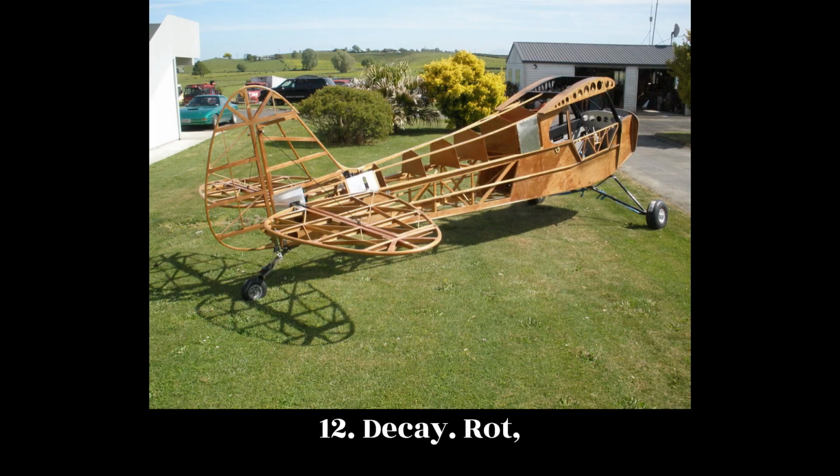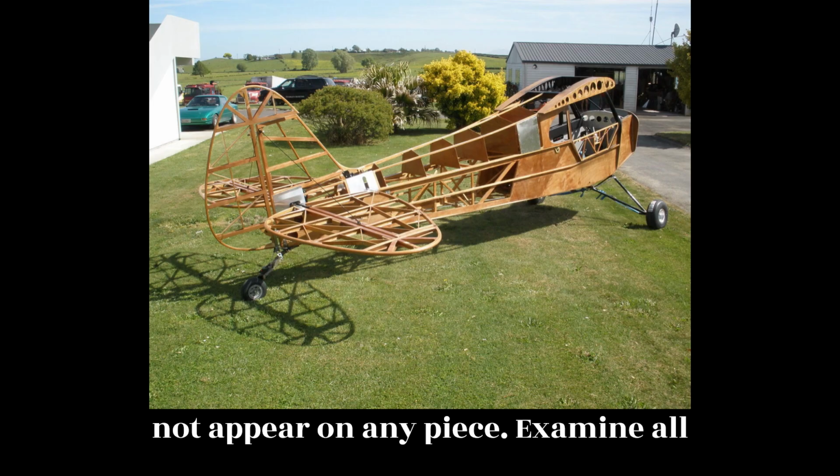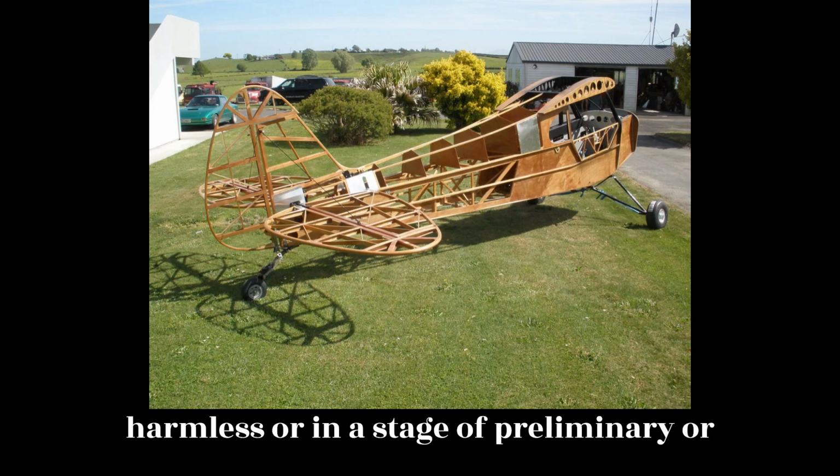12. Decay. Rot, dote, red heart, purple heart, etc., must not appear on any piece. Examine all stains and discoloration carefully to determine whether or not they are harmless or in a stage of preliminary or advanced decay.